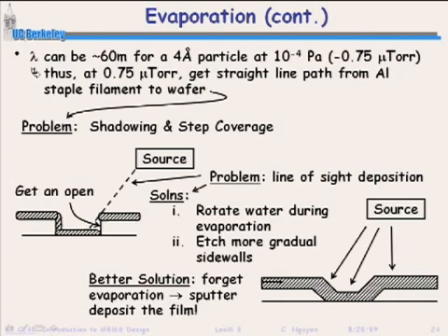So in essence, a lot of oxide etching recipes that they have for semiconductor equipment are designed not to get straight sidewalls, but to get angled sidewalls. Because usually the next step after oxidation is cutting vias so that you can make electrical contact from one layer to another. Oftentimes these aren't good enough, though. So what's a better way to put down a film? Another way to put down a film is sputter deposition.